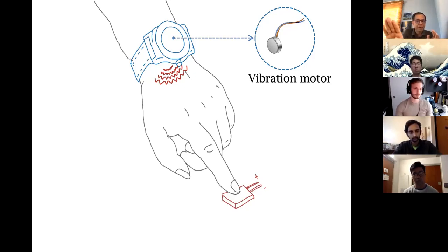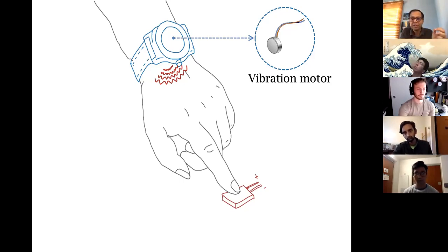Right? If you touch that vibrating mass, you will feel a vibration. And if you take the FFT of that signal, you should see a bunch of frequencies and magnitudes of that FFT. And maybe a phase as well, depending on where the magnetic mass is starting from, that will be the phase. So you see how we are connecting things from FFT to acoustics being vibration, to now a vibration motor, which just has a magnetic mass which is moving back and forth inside a coil.